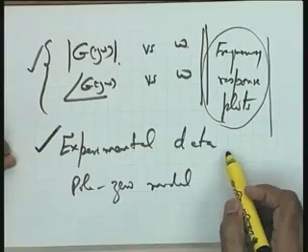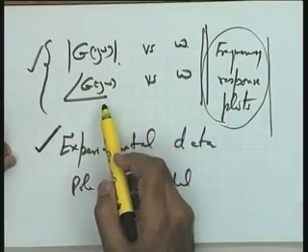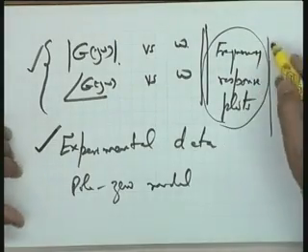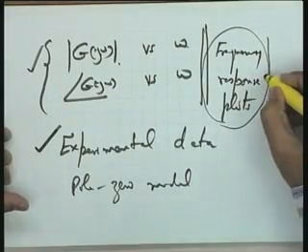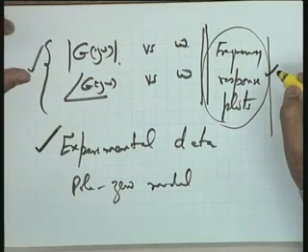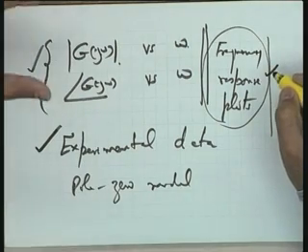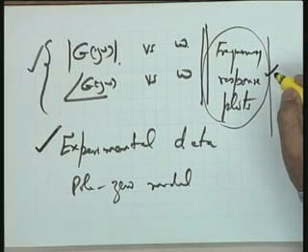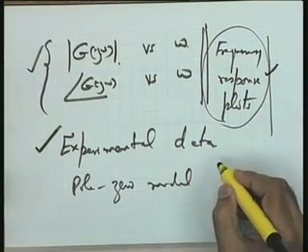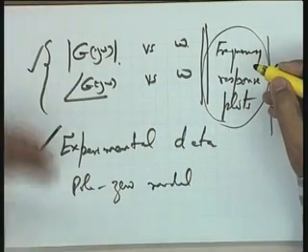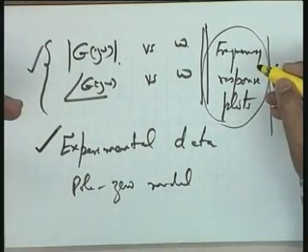Subject your system to sinusoidal testing, obtain the magnitude and the phase angle, and use this frequency response data to get the frequency response plots. These plots, which have been obtained directly from the system hardware, are a complete characterization of the system. You really do not require the transfer function model or any other model for analysis and design. This is a very important attribute of the system, because the modeling of a system is a very difficult exercise.